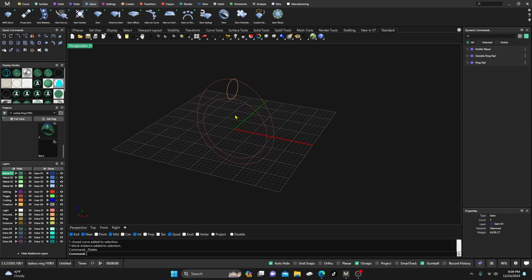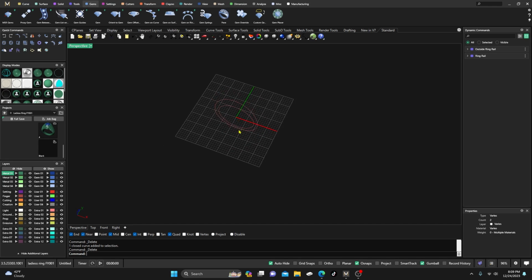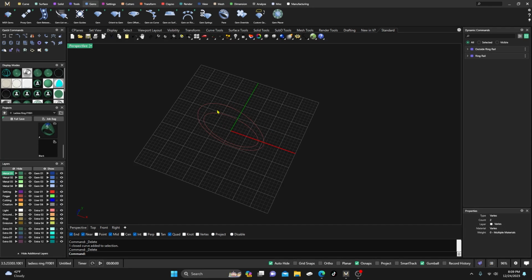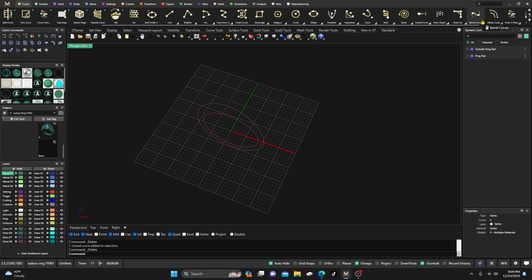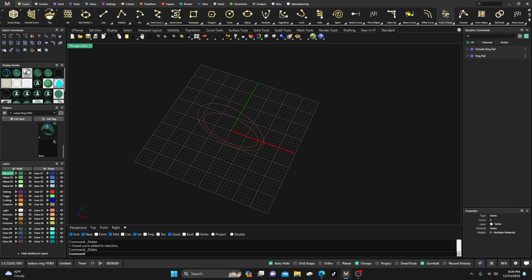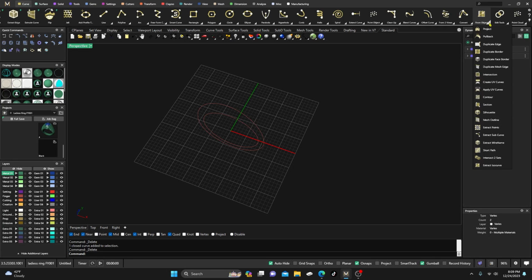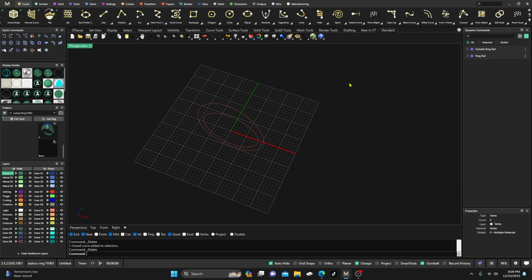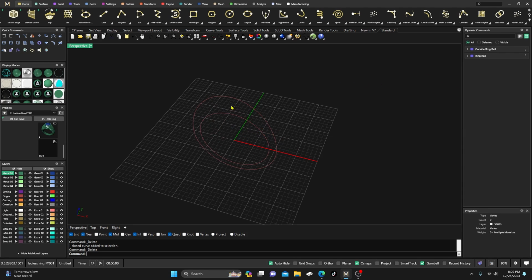Let's get rid of this gem here. Let's get rid of this profile. And your other question was on create UV curves in Matrix 8, right? First of all, the create UV curves is in MatrixGold, of course. It's all the way down here in your scroll. You scroll through your ribbon here, go all the way to the end, from object to your drop down. Create UV curves is right here. But really, there's a much easier and better way to do this.